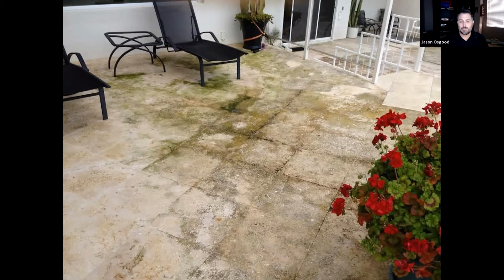99 out of 100 times, if an issue happens where there's mold and mildew on the paver, you pull the paver up, I promise you that base material, that bedding sand, is soaked because there's nowhere for that water to go. So this is why we really stress, take your time, do the base correctly. When you do the base and the bedding sand correctly, when you compact it right and you hit your elevation and your pitch properly, you should not have any problems.